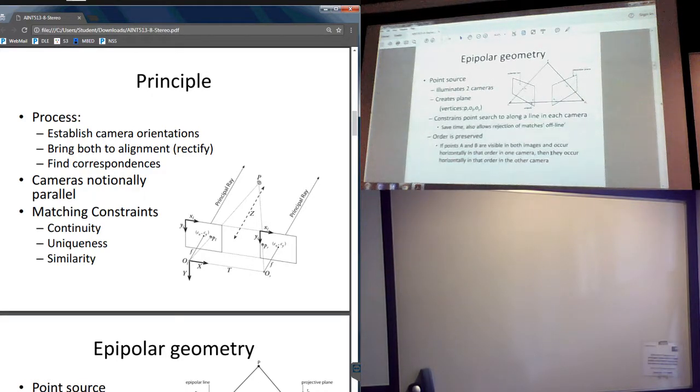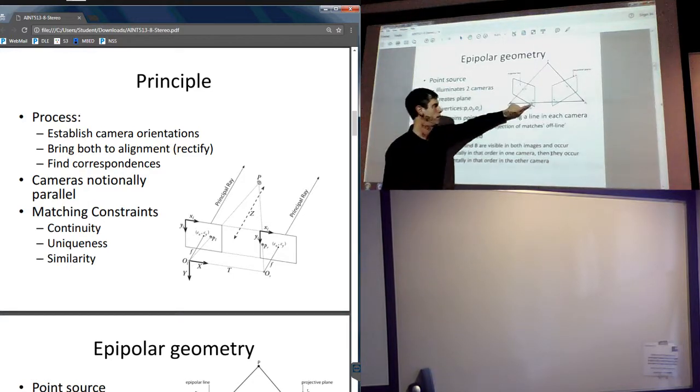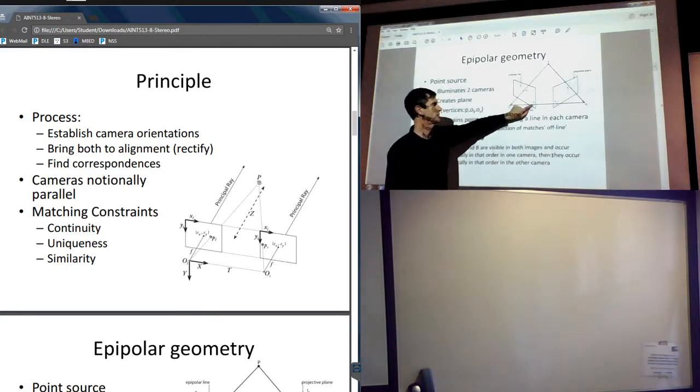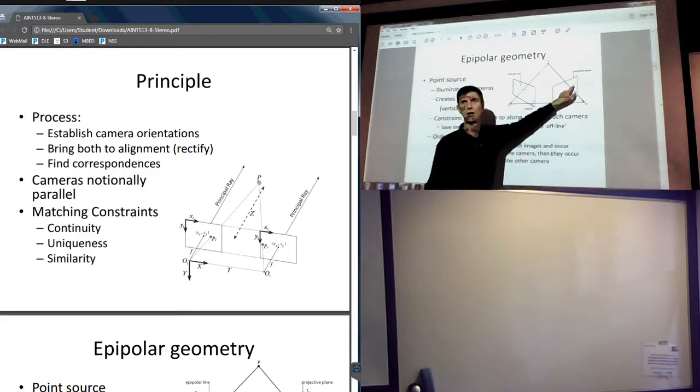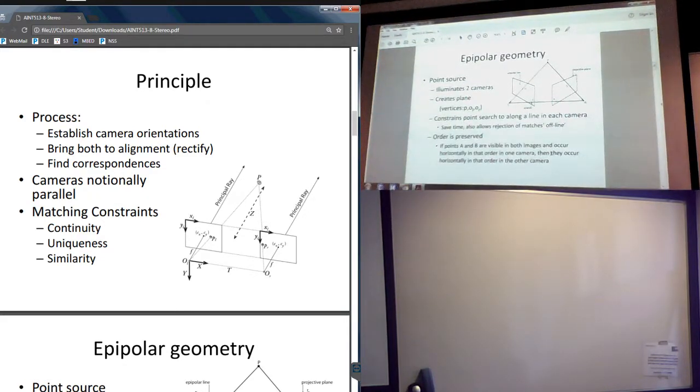We do this geometric analysis because, having made this calibration, there's an assumption that we don't move the eyes. So the eyes are fixed on some backplane, and if you look at passive stereo cameras, they're all cameras fixed to some metal bar that points them forwards and doesn't move them. And the reason for doing this is that it saves search time, because once you know what that line is, you only have to search along that line to find a match between the two cameras.